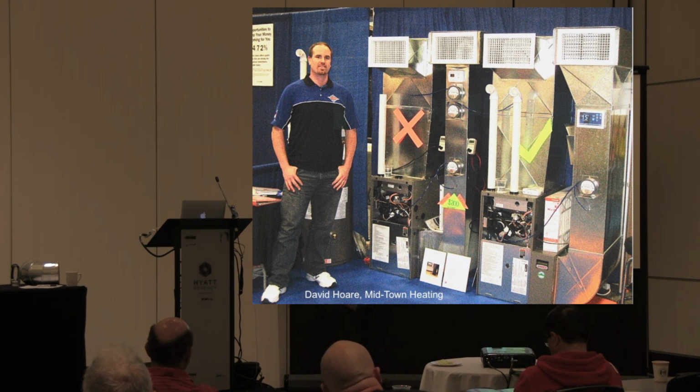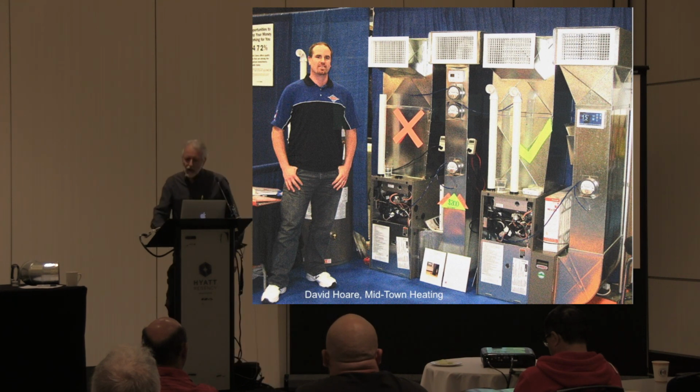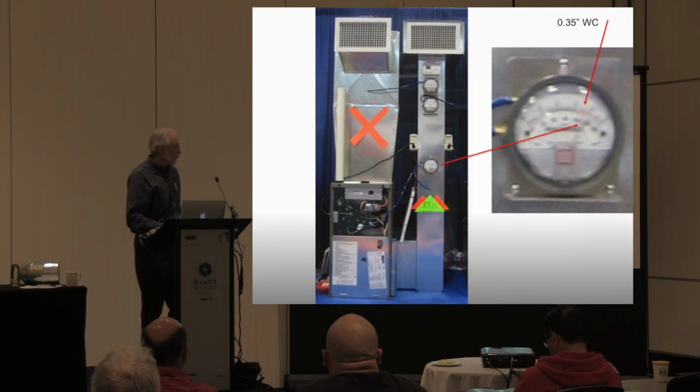What he had here was a 1-inch filter with standard mounted, sharp throat, standard return, everything was normal, versus radius throat, turning vanes, and a big filter. And these gauges here show what happened in getting air from here 3 feet away, actually inside the appliance. That's how the appliance sees it. How hard did it have to work to do the job? My photographs suck, but I think with a little bit of cheating, you can understand where they're at.